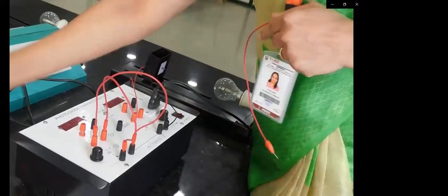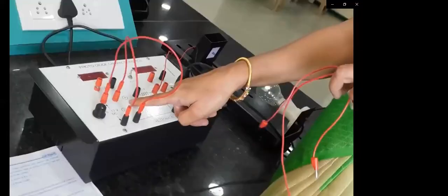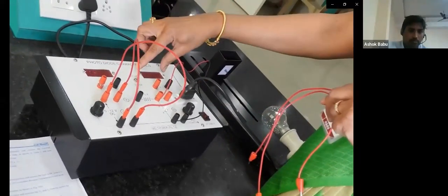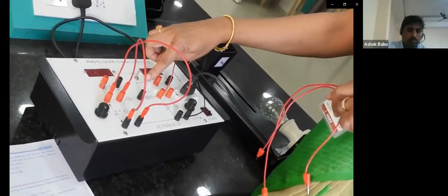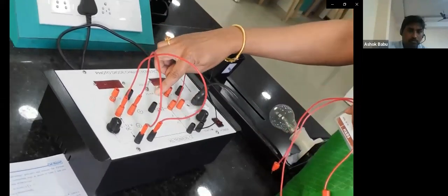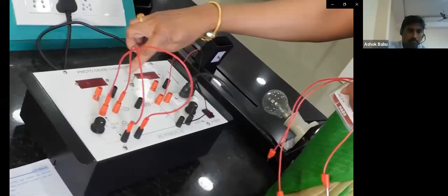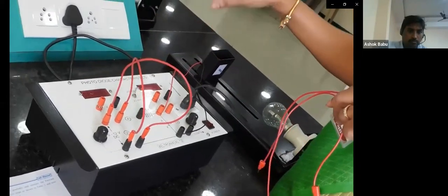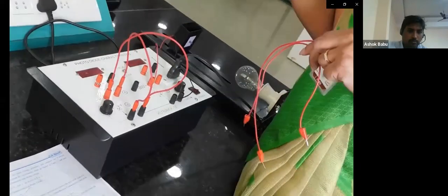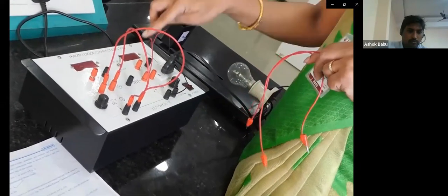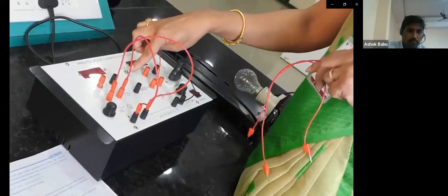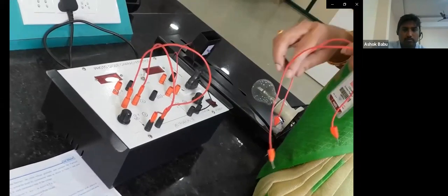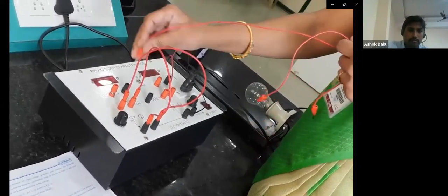Now let us connect the ammeter. Ammeter is used to measure the current in the circuit. Here, as I told you, the ammeter is inbuilt and we have a provision to measure the current in milliampere or microampere in the range of 200. Because we are using it in the reverse mode, the current is always due to the minority carriers. Therefore, it is very small. We measure the current in microampere. So, let us put it in the microampere mode and connect the ammeter.